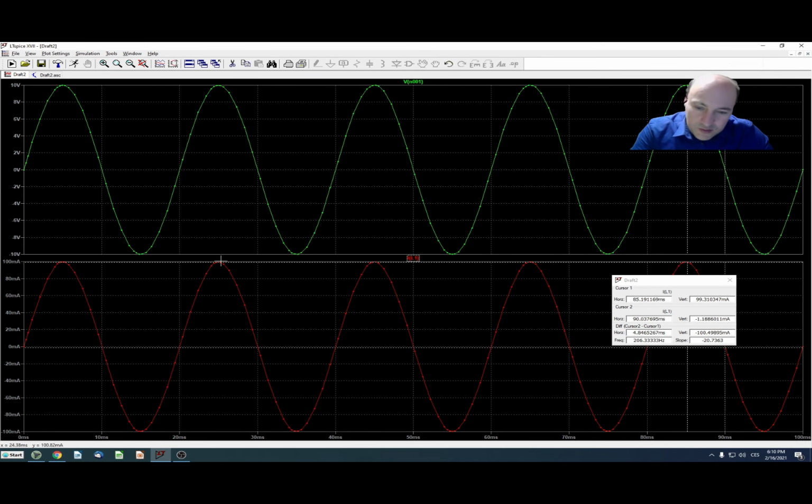So we're back at what we've seen originally. We have a sine wave of voltage and a sine wave of current, and there is zero phase shift between the voltage and current. Now, one of the reasons why we are doing this in LTspice and not in PartSim like last semester is that in LTspice we can do some calculations with our signal.